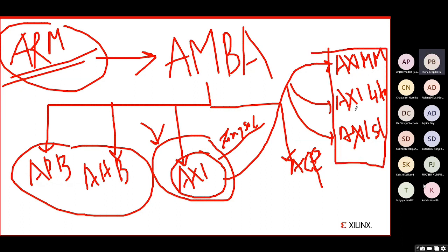This is the second thing we need to focus on, because let's say I'm making n number of peripherals, but the main objective is that at the end of the day, we need to communicate through AXI ports. So all those ports should be AXI enabled. When we do the labs, Xilinx has already provided all those AXI based IPs, so it is easier to connect with the ARM processor now.